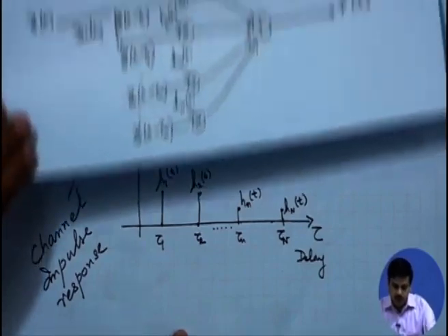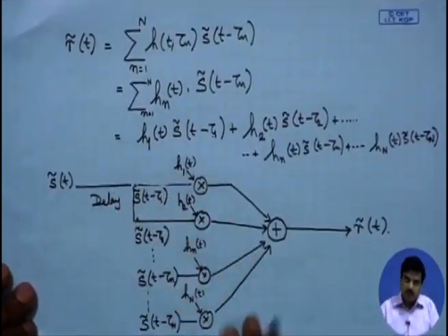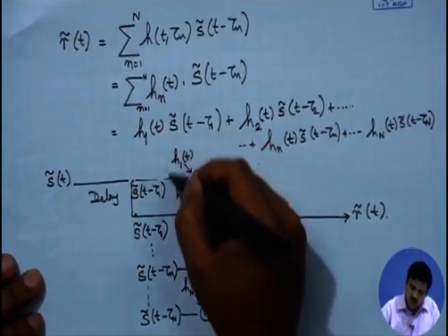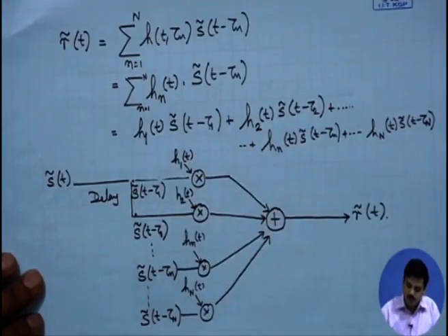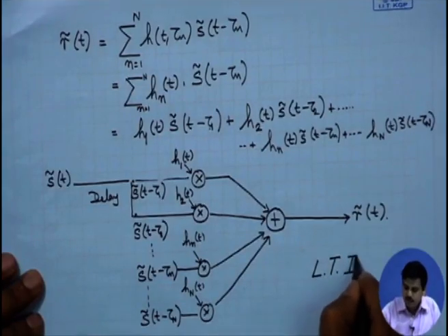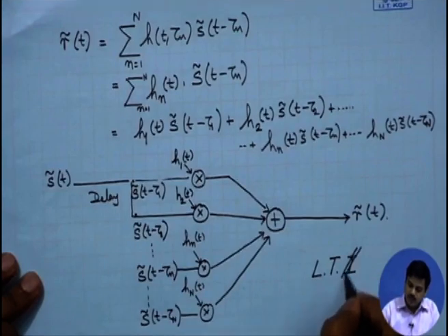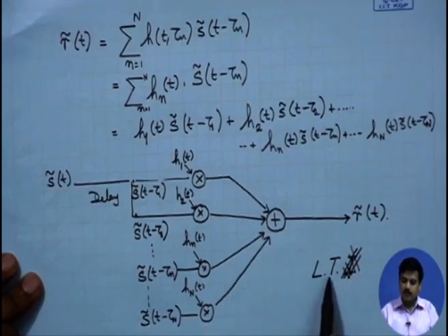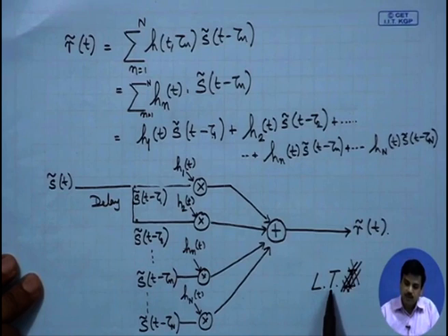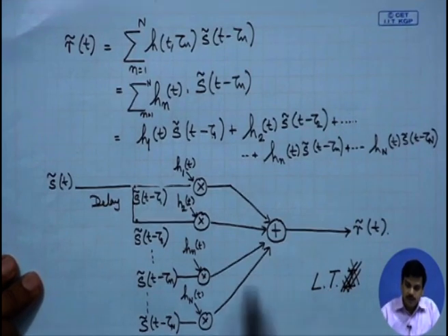What you may have encountered before is such a situation, that means such a filtering, linear transversal filters, where these coefficients were not varying with time. These were constant with time, and you had a linear time invariant system, but what we encounter here is a linear time variant system, and this is fundamentally because of the phase, which is a function of time, and that has happened because of the multipath propagation, where we have mobility involved as part of relative distance between the transmitter and receiver, or the points of reflection, or the surface on which the waves impinge.